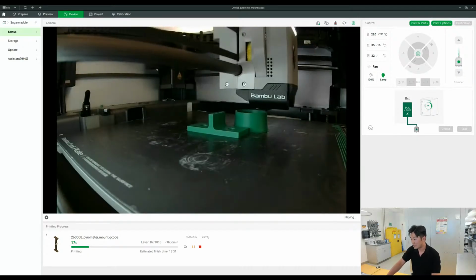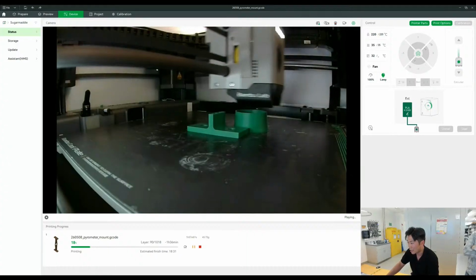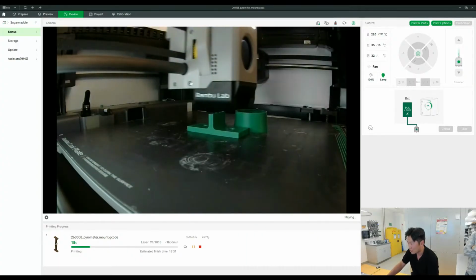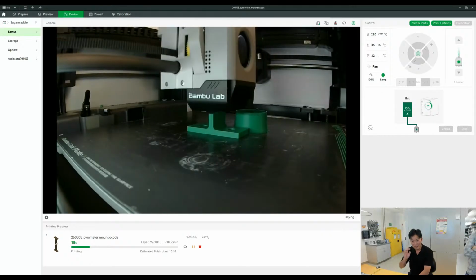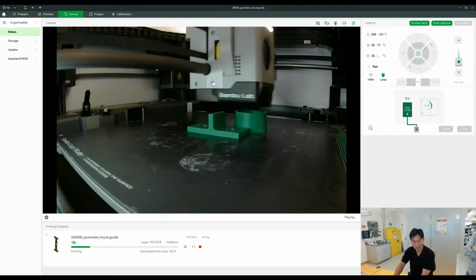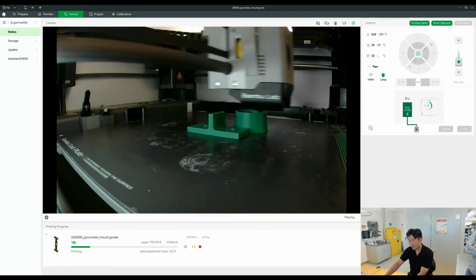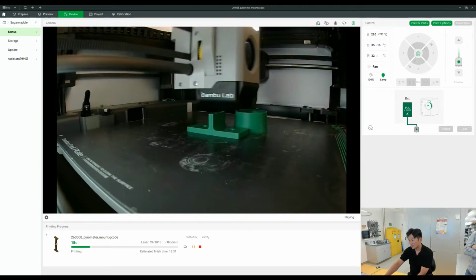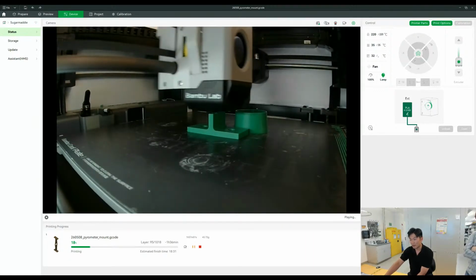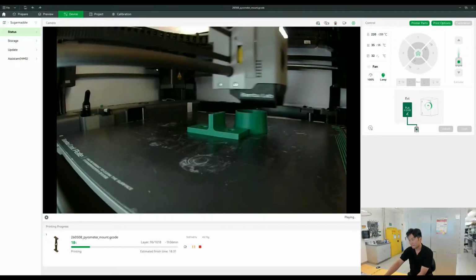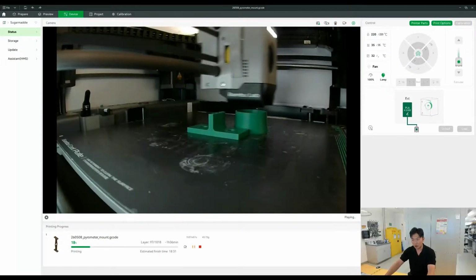Now let's see, this is the issue. See how it's oscillating? It's because right now the output level is 56, which is perfectly divisible by 8, which is the discretization number, the constant that I picked. So it's flipping back and forth. We need to use a different method for the controller. It's working, but it's not really the best. This is as good as I'm going to get right now. It's an oscillation of maybe plus or minus 2 degrees Celsius.